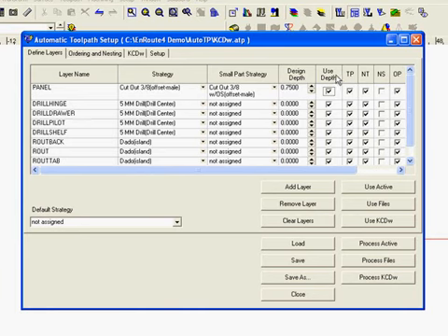The next step here is use depth, which means we are going to read the depth off the Dxf files. TP means toolpath. NT means nest together. If all of my parts were in one Dxf file and each part that I wanted to stay together was grouped, I can nest these separately and process just a single Dxf file. But since each part is in a separate Dxf file here, we're going to choose nest together. And finally, I have output, which means it's outputting the file to en route, or that particular layer.